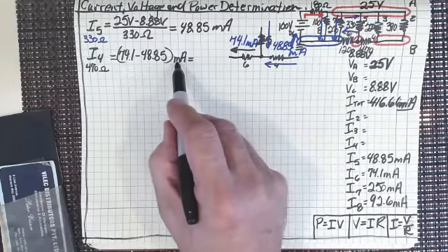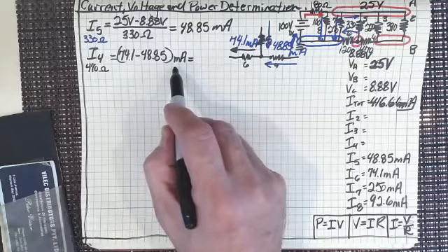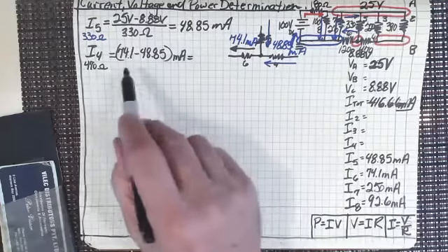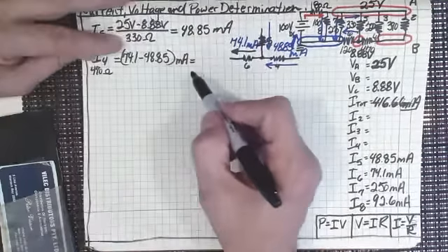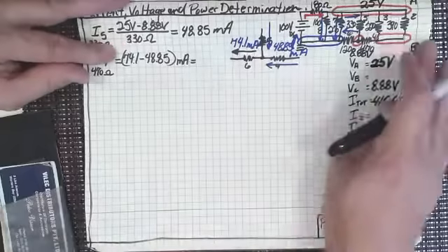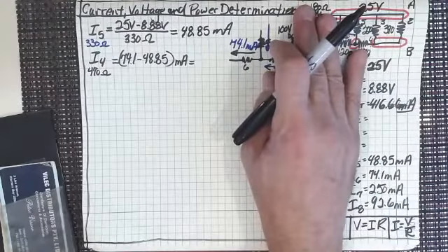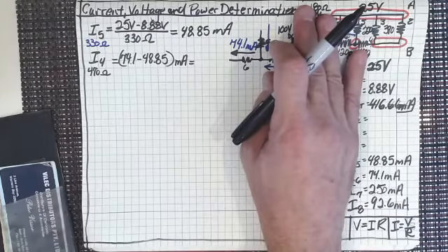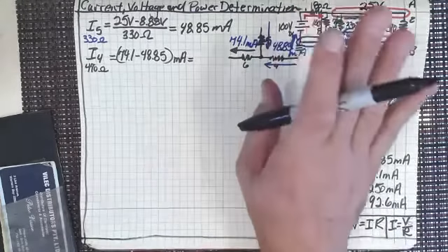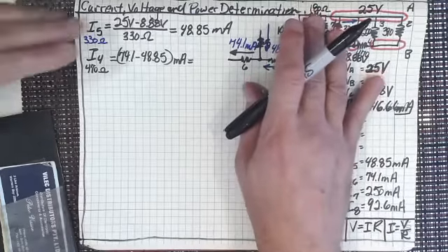Because here you've always got to use that times 10 to the minus 3, you've got to put it in there. A lot of people don't. They just multiply it through by milliamps and think, oh, later on I'll divide by 1,000 or whatever. And in fact, they end up dividing where it should be multiplying and multiplying where they should be dividing, and the spaceship goes off into nowhere land.